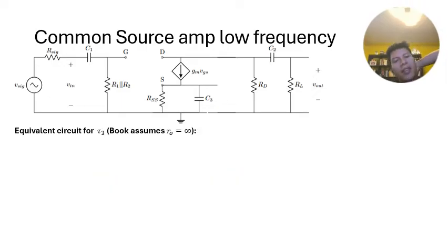All right, so to calculate tau 3, we again take our circuit, we short out all the remaining capacitors. Since we're finding our Thevenin, we can short out external sources, and then we just need our Thevenin 3, looking into here.